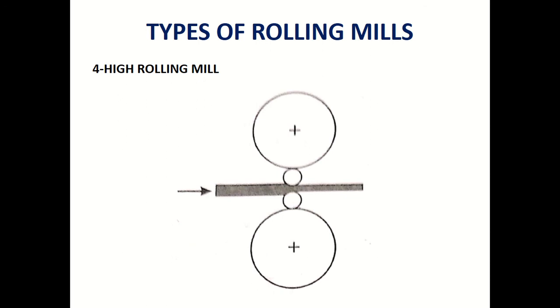Okay, and if you do so, it in turn reduces the load bearing capability of the rollers, and otherwise it may cause failure. So how can you manage this situation? This condition can be avoided by using backup or supporting rollers.